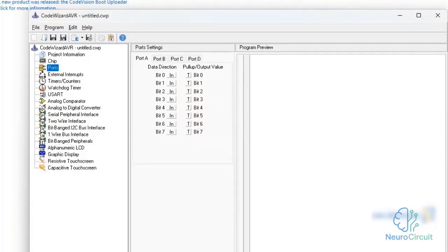But when we want to set a pin to output mode, for example, to connect an LED to it, the microcontroller is sending output to the LED, so that pin should be set to output mode. So we set that pin to output mode. Now we want to connect an LED to pin 0 of our port A, so we set that pin to output mode. On the other hand, those pins can be either 0 or 1 when they are in output mode.